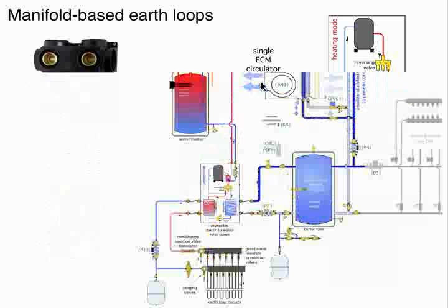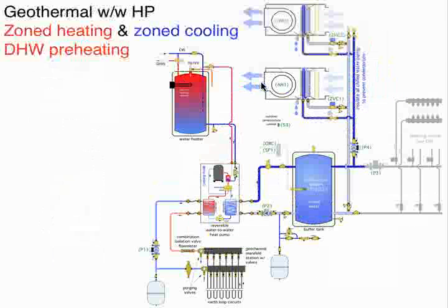Real quick, here's a schematic that shows zoned heating and cooling. And you'll see both the heating over here, which is grayed off right now. We're assuming we're in a cooling mode operation, so the heating's grayed off. Here's our zoned chill water air handlers. They are being supplied through the buffer tank. The heat pump can switch between heating and cooling mode.